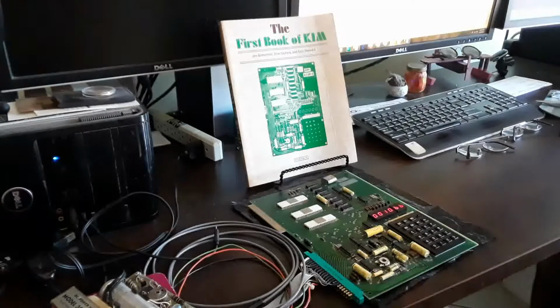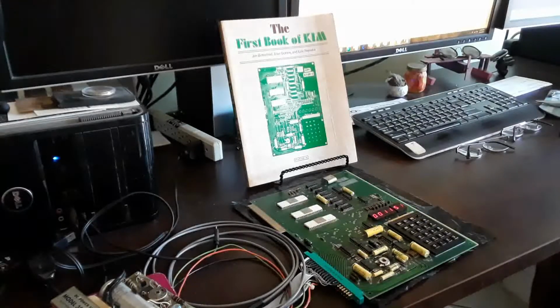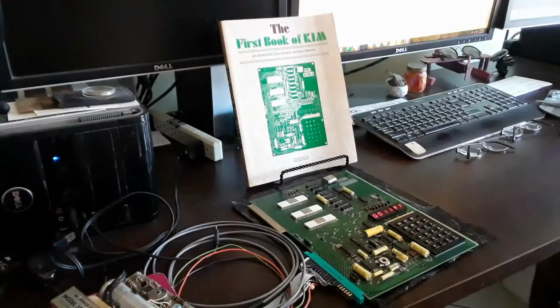Now let's change the value by going back into data mode by pressing DA again and enter the value 00. Then hit the plus key to advance to the next memory location. As we are still in data mode, we can simply enter the new value that we want to appear at this address. In this address, I'm going to enter the data value FF.